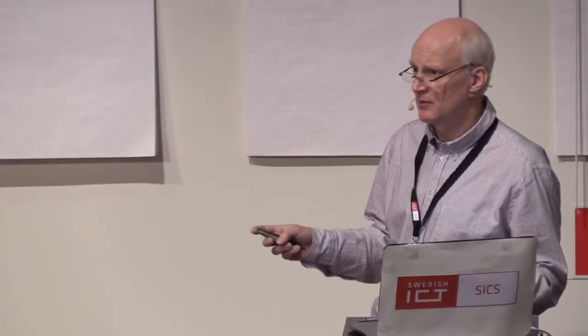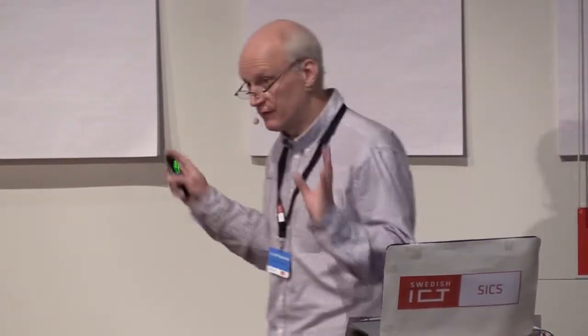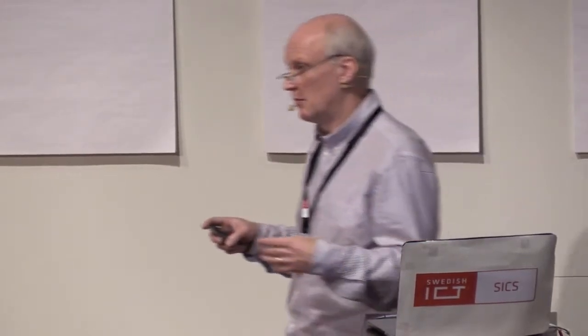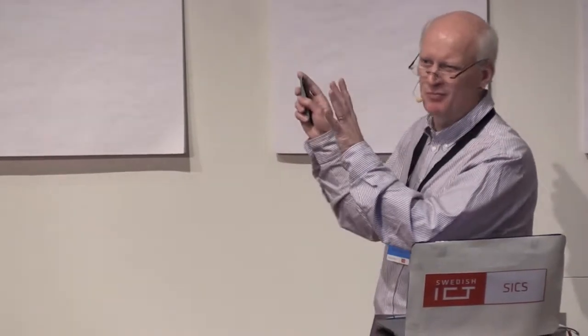And to boot that on a detailed model, it would require weeks of wall clock time to do. So that wasn't realistic. So what did they do? Well, they booted the system on a full system simulator, which has a simple model of the processor, but it's complete, right? It modeled the whole system, and they positioned the workload. Then they took the state of this simple, essentially multi-core model, moved that to the detailed model, and hooked the detailed model into the simulation, kept the other peripheral parts that weren't used anymore, or not that much at least, and ran their application.